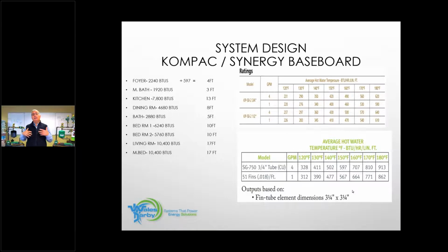That will indicate to the circulator what the air temperature is, and return water temperature. If you want a 20-degree delta, that could speed up the pump much more and increase that flow rate. We can get that coil up to temperature faster. We've got a couple of tricks to get around it, but mostly I would concentrate on getting the proper coil that will give you a high output at low temperature. Anything else, John? Good.